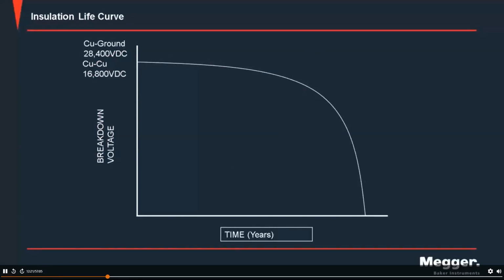All right, so again, to understand insulation failure, we have to understand the prime motivation for insulation failure, and that's going to be the insulation breaking down. And so the insulation starts at a very high value. This is by design, right? So we have a motor nameplate rating, say a 460 volt motor, for example, and that rating is related to the operating voltage that we'd apply to that motor. But there's also an insulation voltage rating.